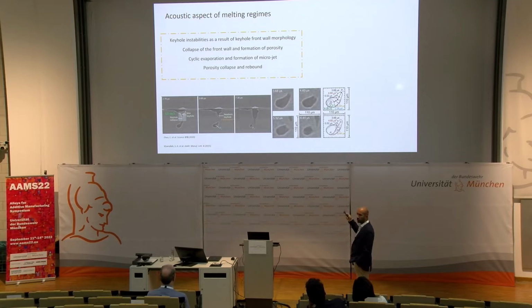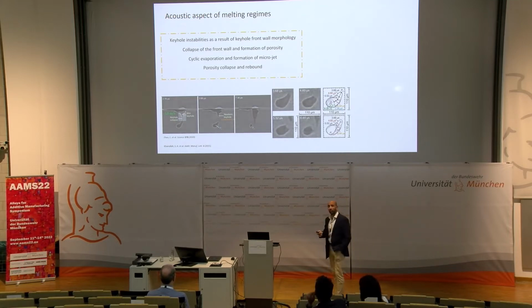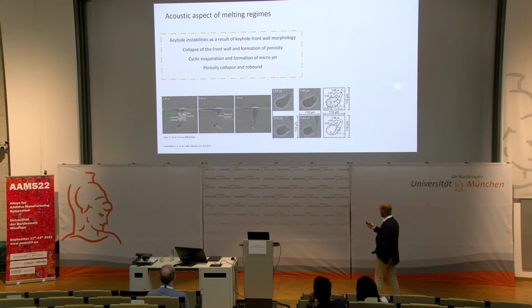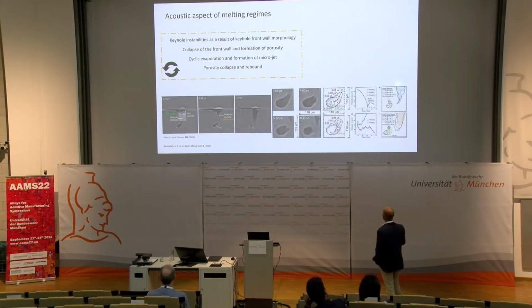They call it water hammer pressure, which can reach values of 140 to 150 megapascal on one side of this small porosity. So, of course, we think that they create a sound, and we would like to see if we can hear it and somehow recognize it in a time-resolved manner.